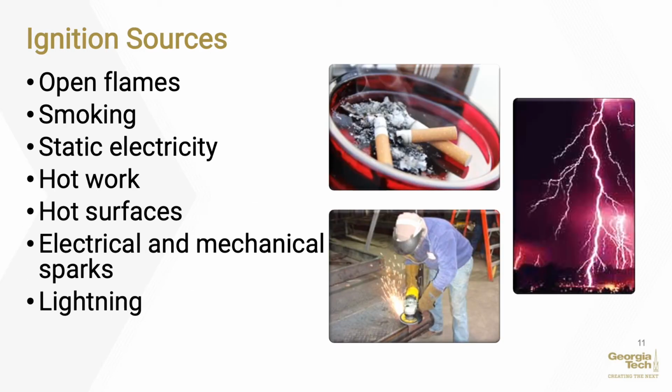Ignition sources can include any material, equipment, or operation that emits a spark or flame, including obvious items such as torches, as well as less obvious items such as static electricity and grinding operations. Equipment or components that radiate heat, such as kettles, catalytic converters, and mufflers, also can be ignition sources. Fuel sources include combustible materials such as wood, paper, trash, and clothing, flammable liquids such as gasoline or solvents, and flammable gases such as propane or natural gas.